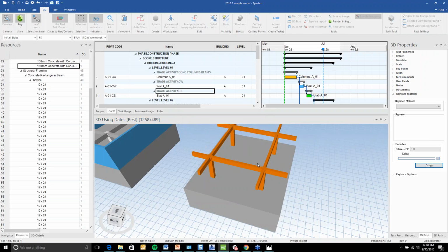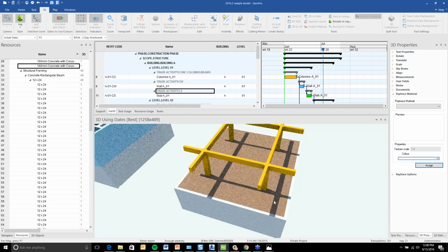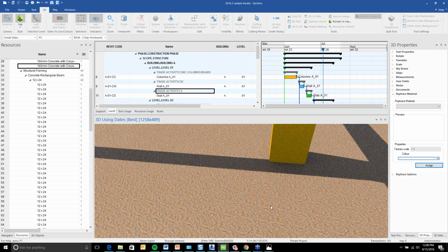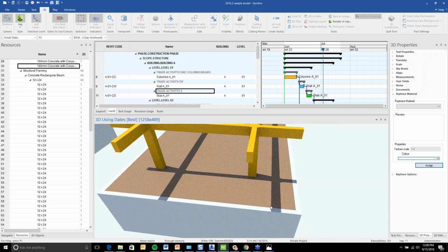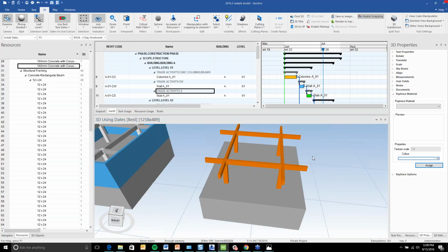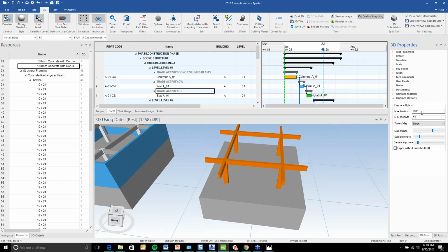and then when you render it, you'll get that material. So it gives you a bit of flexibility within Syncro now to override some basic texture maps for the purpose of ray tracing. And then in addition to the materials, we have some basic controls for sun altitude, brightness, camera exposure, and if you want to export animation data or not.